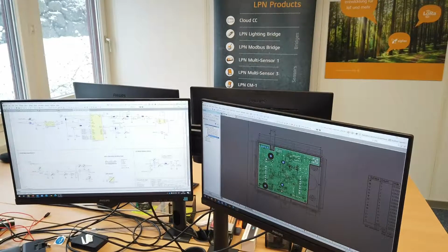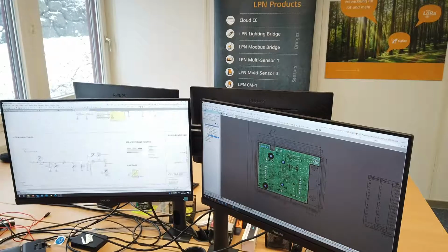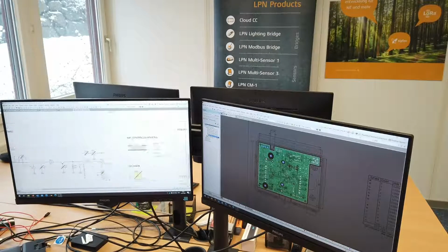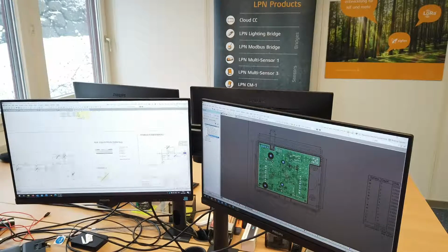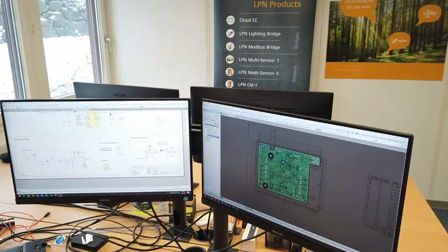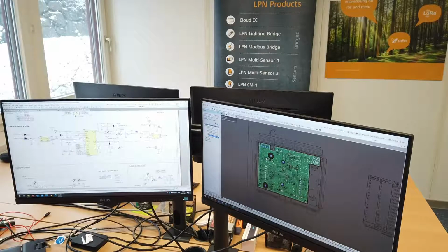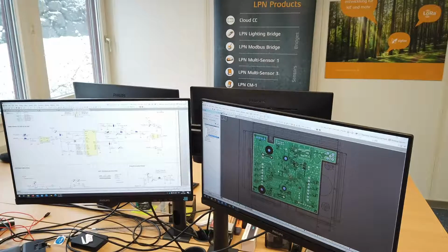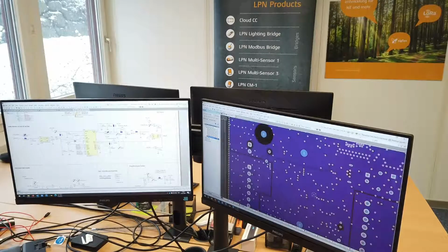The actual energy we can take out of the battery is at the end much smaller than the nominal energy we see on the datasheet. So this is really a critical point for us to know how long our system is actually going to work on that battery. Take special care when choosing the DC-DC converter, as it is not always important to have the highest efficiency, but in our case, for example, as we're battery powered, we need to actually have the lowest quiescent current, as we're always sleeping.